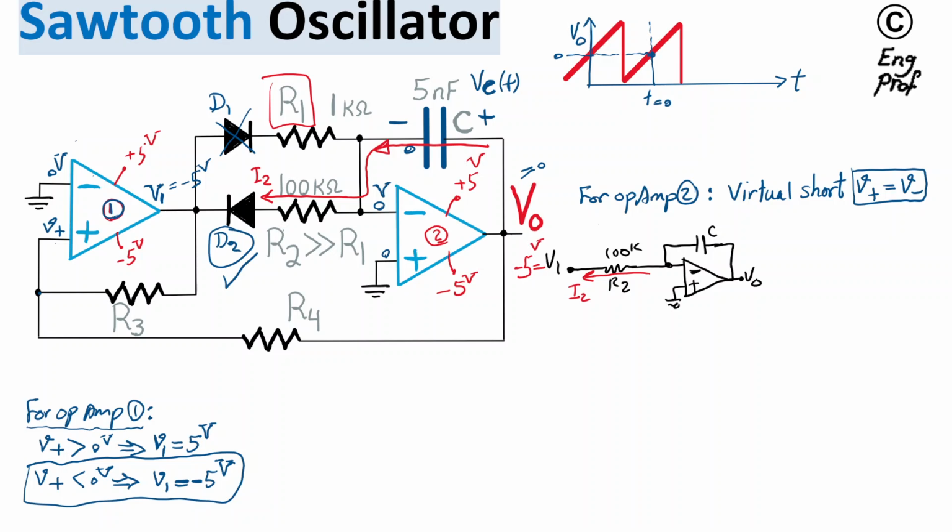So just for the sake of reference, if I continue the plot, let's say I also show V1 while I am showing Vout here on the y-axis on top as a function of time. So there you go, V1 at the output of op-amp 1. At time 0, V1 is negative 5 volt, and as time is increasing, we are at negative 5.